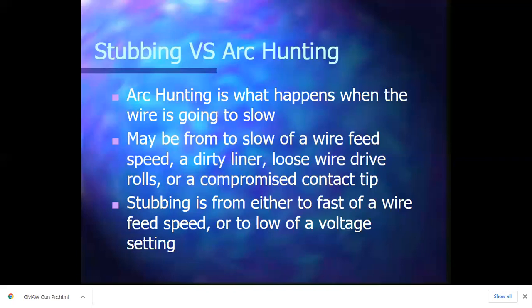So to take care of that, we can turn the wire feed speed down if we're looking for a smaller weld, or if we need that wire feed speed to get the weld size we want, we have to turn our voltage up to match that wire. For every voltage or wire feed setting, we're going to increase the voltage to match it. There's a parallel, or kind of a happy zone, for every one of the settings for wire. And basically, it's our job to recognize these problems and then adjust our settings accordingly.